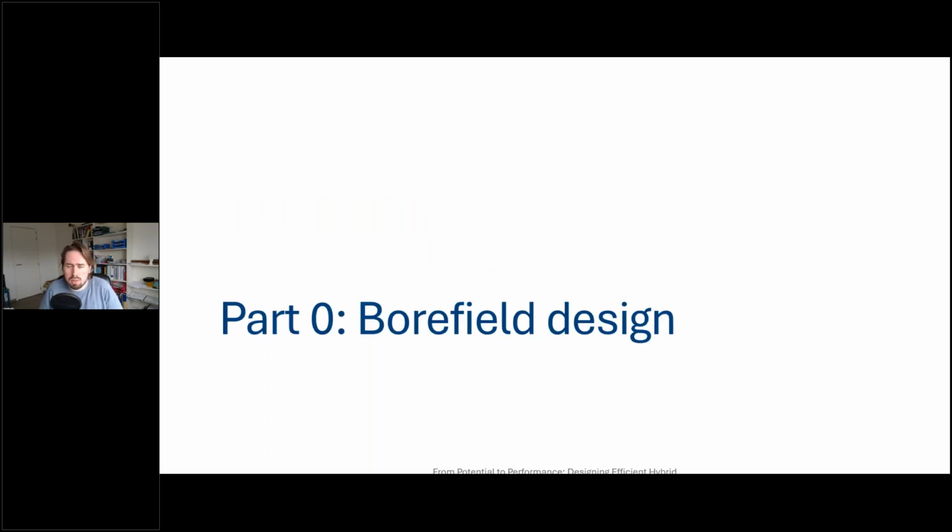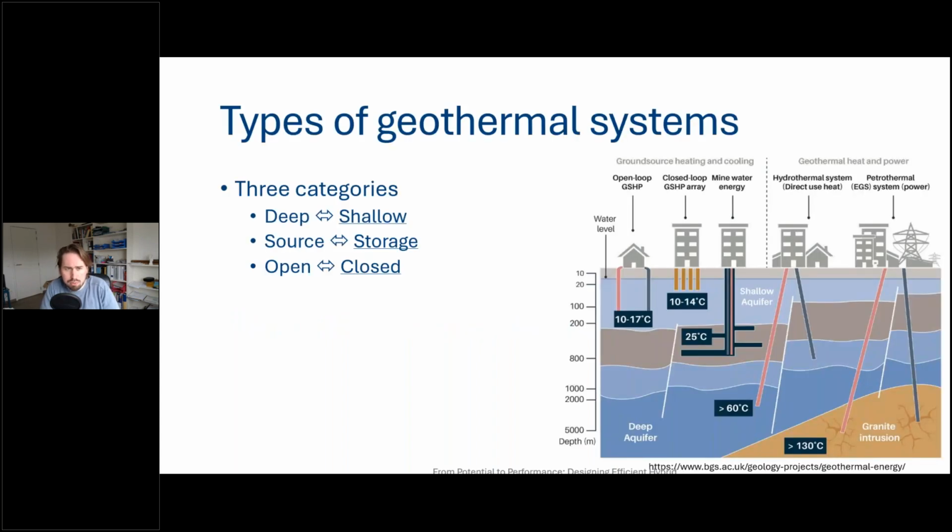So let's get started with the beginning. So within the domain of geothermal systems, there are quite a lot of different technologies, many of which are also featured in this webinar series. For today, we're going to talk about shallow systems. So it depends a little bit on your country on what's defined as being shallow. In Belgium, it's typically everything above 500 meters deep. So these are typically systems which are used to store energy. So at 100 or 120 meters deep, the temperatures typically range from 0 to 25.